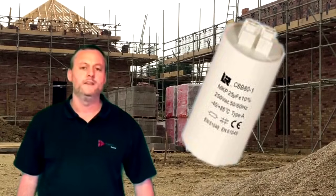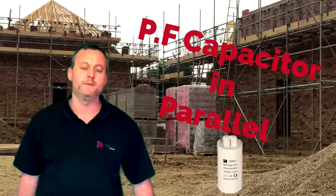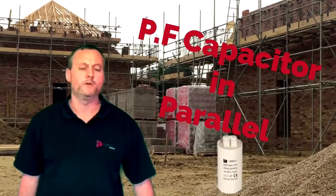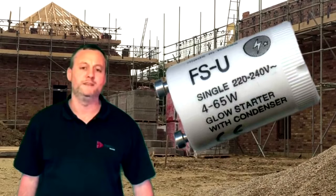Other questions in this section will be about the capacitors. There's 2 capacitors normally in a fluorescent lighting circuit. There is one in parallel with the supply, which is there for power factor correction, which we went on to look at in a small set of notes at the very end on AC theory. Another capacitor is built within the actual starter to limit radio suppressive interference, that crackling effect when the fluorescent lighting circuit is turned on that causes interference in radios, etc.